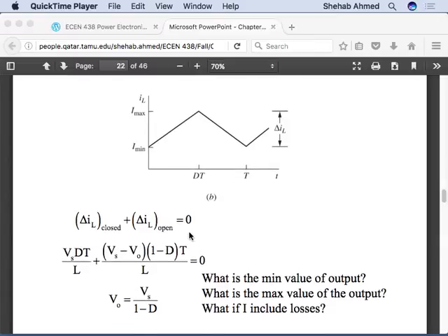We will still have a voltage transfer equation, and that's going to give us the ratio between output voltage to input voltage and duty ratio. Same thing, and we will still calculate inductance and capacitance, and we can still do that from the waveform. Nothing changes about calculating inductance and capacitance. Inductance is always area under the voltage curve divided by delta I. Capacitance is always area under the current curve divided by delta V. It's just that these waveforms will change if my current is discontinuous. The area will be different, right?